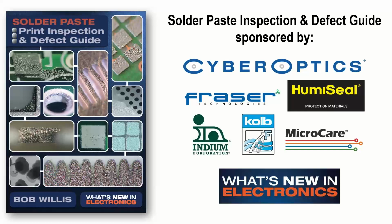If you've got to do it manually, it's a little bit more taxing, but just think about what can I look at on the board which gives us the best indication of the quality of print. Well, normally speaking, the smallest apertures, the finest pitch apertures. So look to those as your reference. So if you find that it's still printing perfectly and it's over the stencil life of the paste, then keep using it. But again, you don't reuse the solder paste if it's not giving you the same sort of performance. That's the one thing you do change.